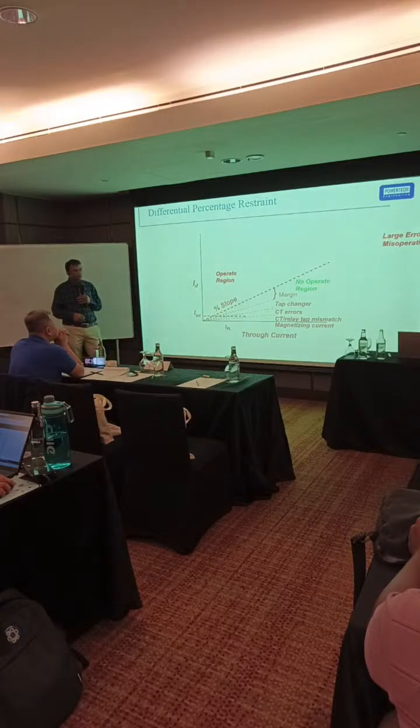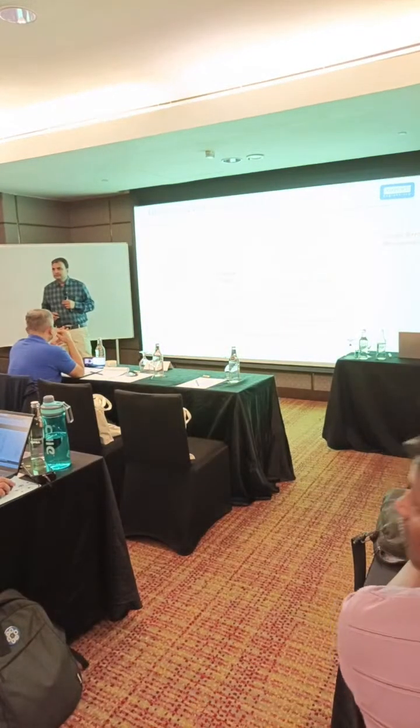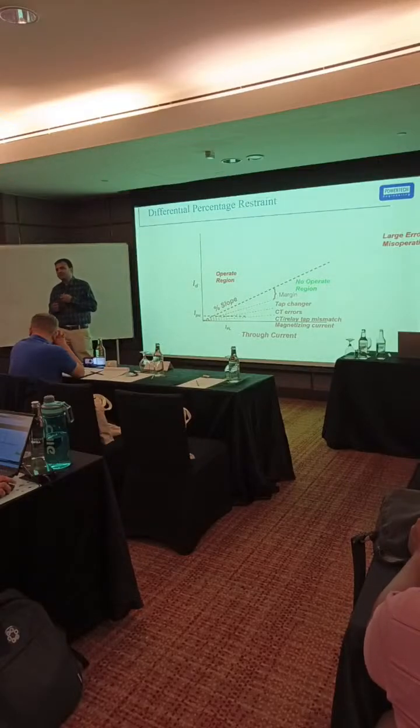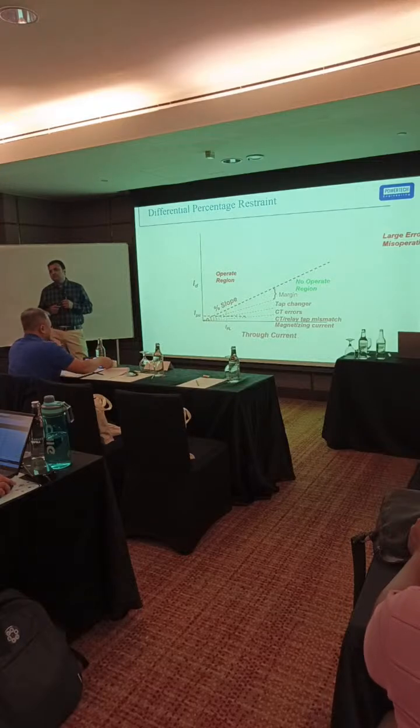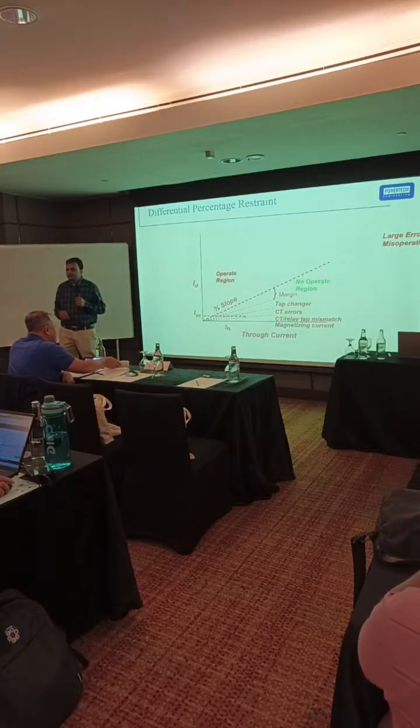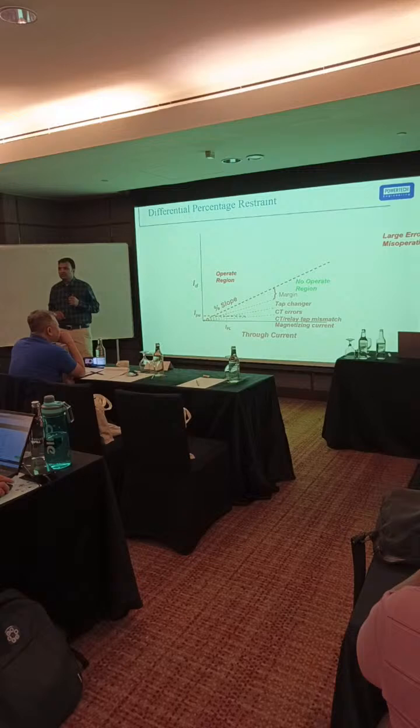Sir, excuse me, sir. If someone sets the slopes wrongly or not too accurately, the pickup will happen every time we energize after shutdown. So without doing anything on the relays, can we keep energizing until the transformer turns on? It happens 2, 3 or 4 times at times. We keep energizing to normalize the system back.